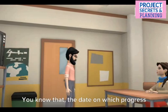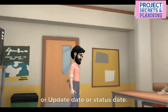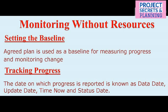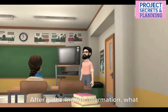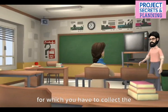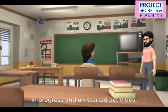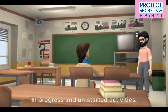Now, I will tell you about tracking the unresourced project. You know that the date on which progress is reported is known as data date or update date or status date. This date is not the reporting date. It is the date till you gather the information from site. After gathering the information, what will you do? There will be 3 types of activities for which you have to collect the information. Completed, in progress and unstarted activities.